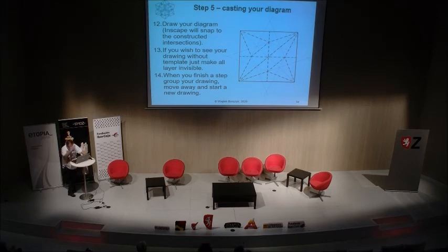I don't know if they are visible, but they are here. And now our drawing has ruler lines. So when you lock the template layer, the template objects cannot be selected, but the crossing points will snap the points of our drawings in another layer.